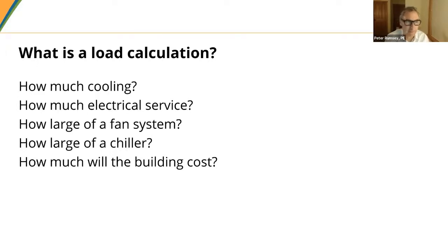So, what is a load calculation? The calculation that we're talking about is figuring out how much cooling we're going to need in a building, how much electrical service we're going to need, how big is the fan system, how big is the chiller or the cooling unit, and all of these things figure into how much will the building cost, which is ultimately a very important thing.